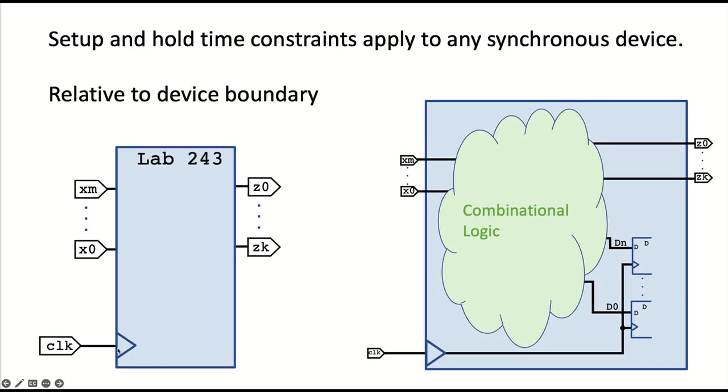Now, if we look inside, the clock actually has to travel inside and probably go to some flip-flops. And so what's happening here is it's translating the time of these constraints and adjusting it according to the delays, which gets you something interesting.